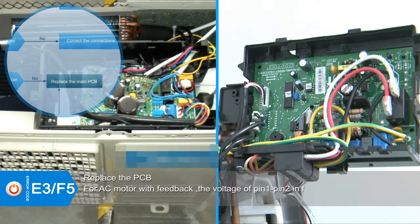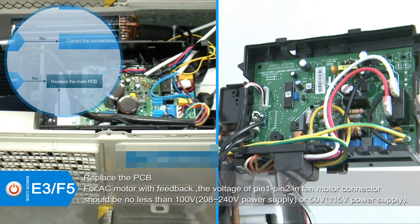Examination for main PCB board. AC motor with feedback. Turn the power on and set the unit as running in high-speed mode. 15 seconds later, measure the voltage of pin 1 to pin 2 in the fan motor connector.